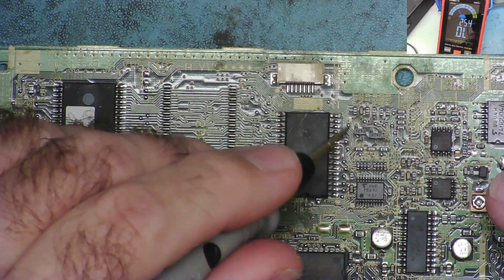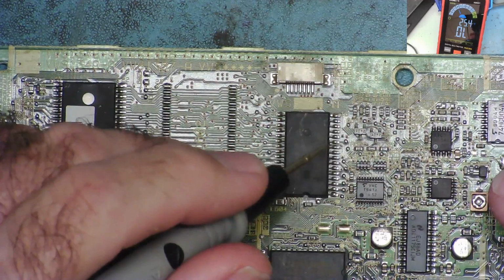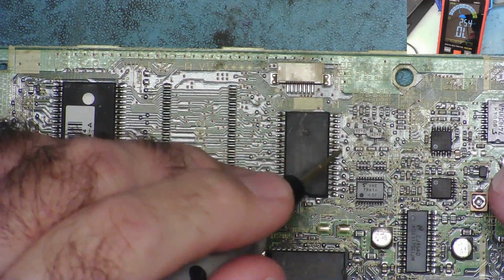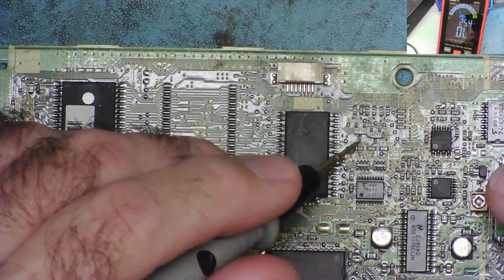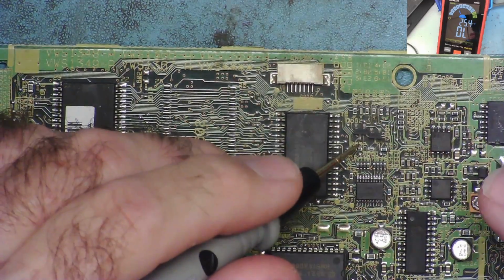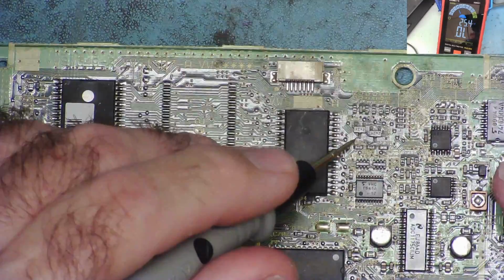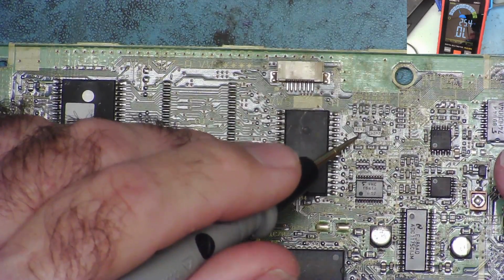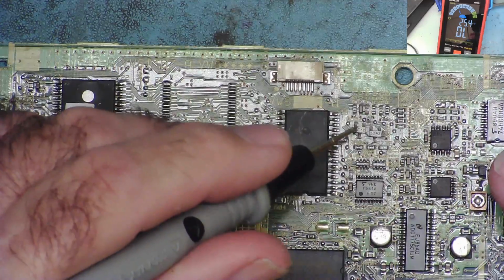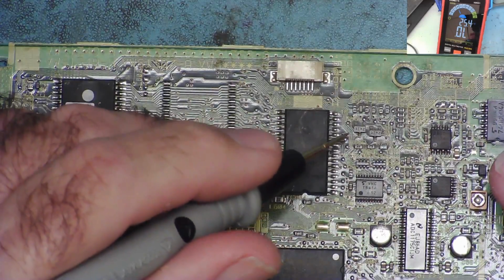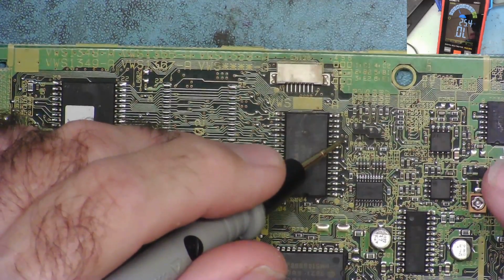2.3 is the size, 2 millimeters by 3 millimeters. And you find a number of other larger packages, especially for higher powered components. So these could be SMD transistors. But the problem is that there's lots of devices made in this package. They could be MOSFETs, which we'll do another complete tutorial on. They could just be diodes, either a single or a double diode in the package. They could be a bipolar transistor.